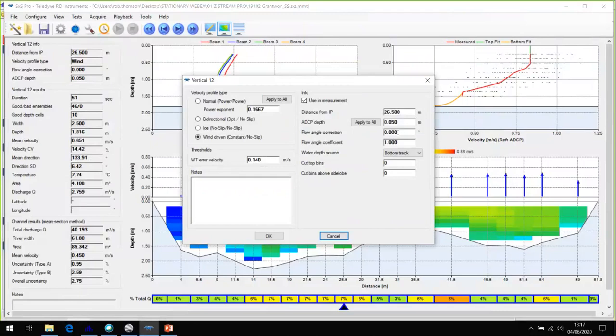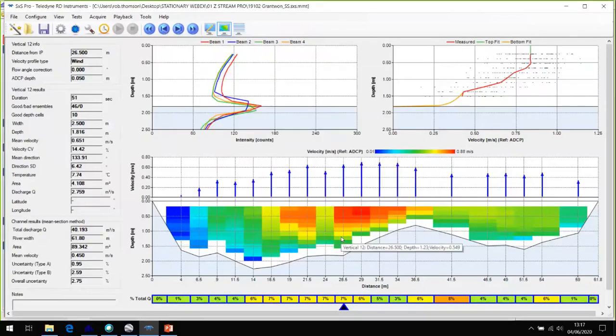But it's also because it's the X component, the downriver component of velocity, that we need to know to calculate discharge correctly, isn't it? Whatever the orientation of your boat, if the flow at that location of the river is quite skew, as with that first slide where you had the blue arrows and the red arrows, the red is always longer than the blue one, because the blue one is just the downstream component of the red arrow.